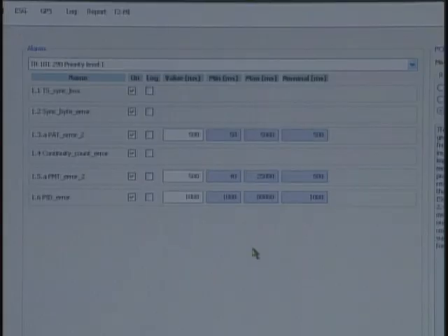Okay, we're going to discuss the settings menu for the ETR290 and just briefly skim over it, since a lot of the settings are very similar to what we did in the bitrate section. You'll see this has to do with alarms, and you have different alarms and different thresholds you can set. Under the PAT error, continuity, PMT, etc., you can set different priority levels.